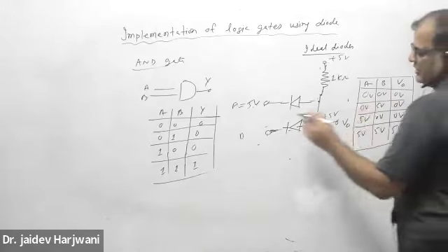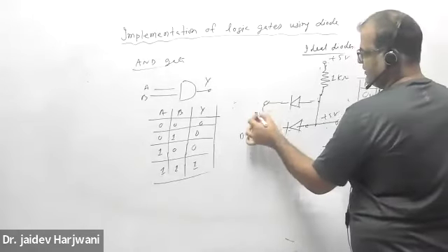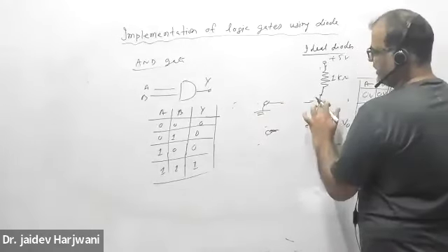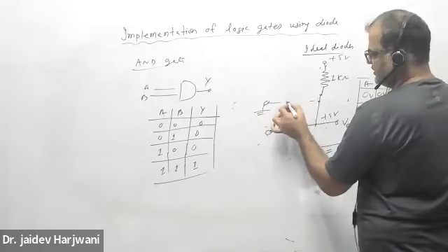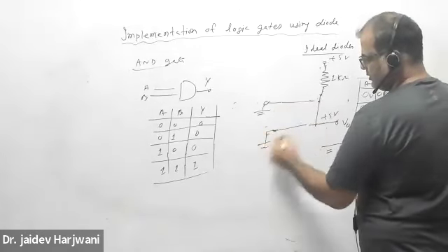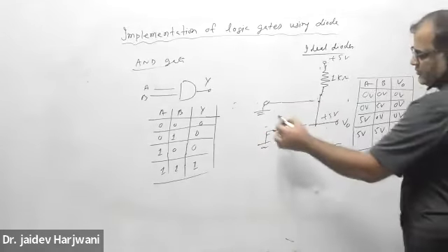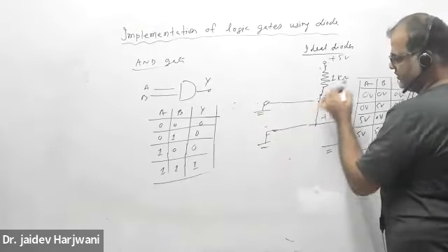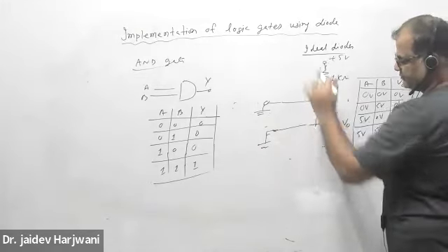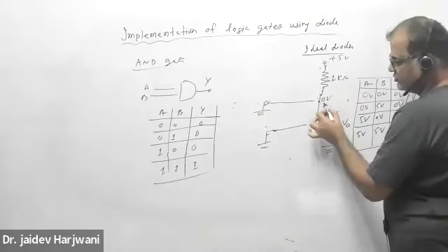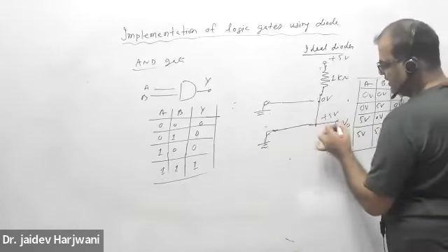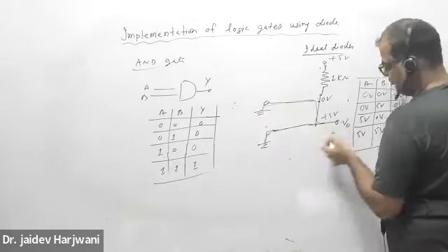Yes sir. So if this is 0 volt, that means this is the ground, because this point is high and this is low. The open circuit voltage is making it forward biased. This is also ground. So now this point is 0 volt, and this is also ground, so all the voltage gets dropped here. Now V naught is directly connected to the ground from here and from here. So V naught is 0.